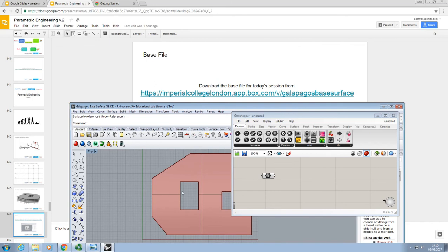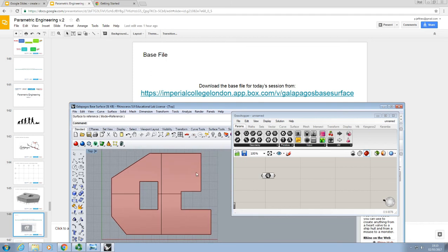see this surface here. So this represents a building footprint with a slightly irregular outside facade line, and then a big hole in the middle of it, which maybe is an atrium, maybe it's a set of escalator spaces or stair spaces, or possibly a service hole. A lot of the time you'll have to deal with penetrations through your slab like this and adjust your structural arrangement to fit around stuff like that. So this isn't too ridiculous a shape. It represents something that you might come across in reality.